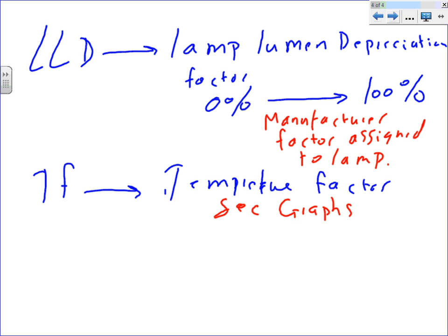or temperature. If you look at page 42, lumen characteristics of fluorescent. This one is for fluorescent. Every fixture has its own. Fluorescent lamp with temperature variation. Look at the degrees, plus or minus 100% plus. This is the percentage of mean rated lumen, how it's going to be affected. If you look at plus 40, these are in Fahrenheit. Plus 40, you get 100% of lumen.